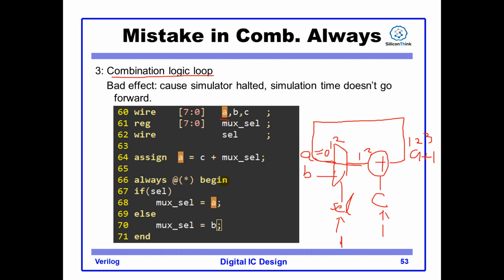From the view of Verilog language, it's an event trigger language. So you can say when cell is 1 and there is a value change at A, this block will be triggered. Yes, this always block will be triggered and cause this signal to be updated.